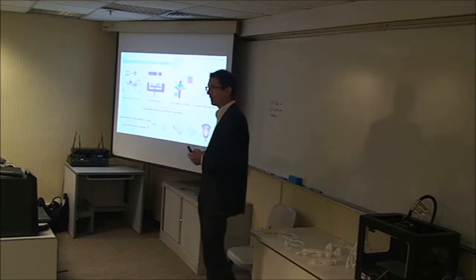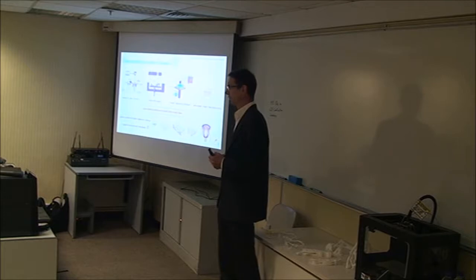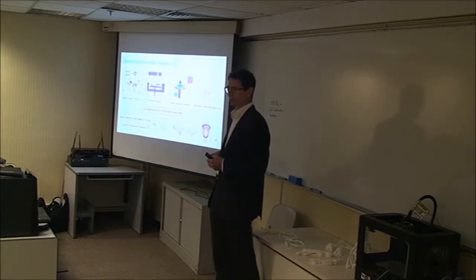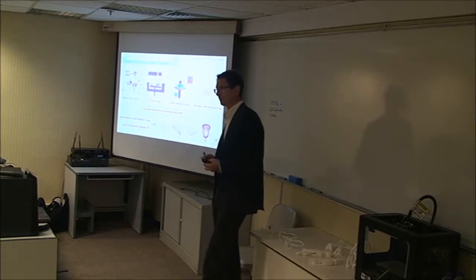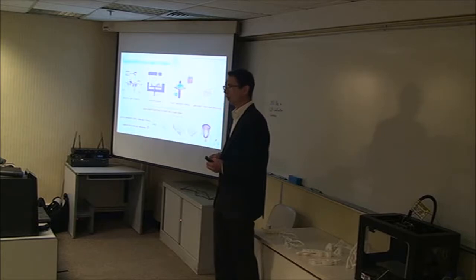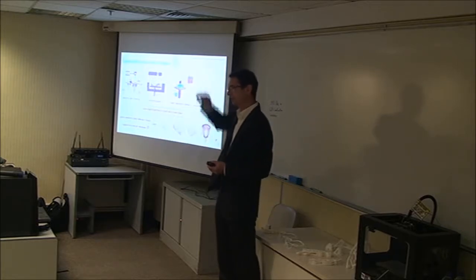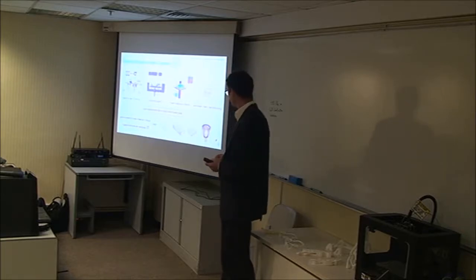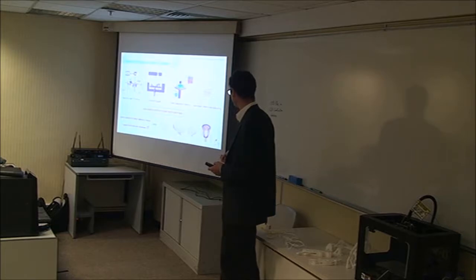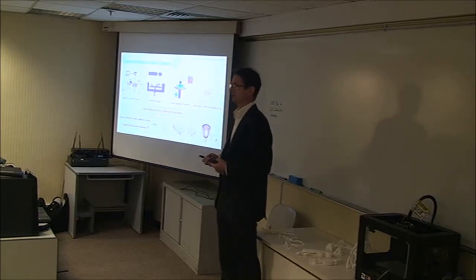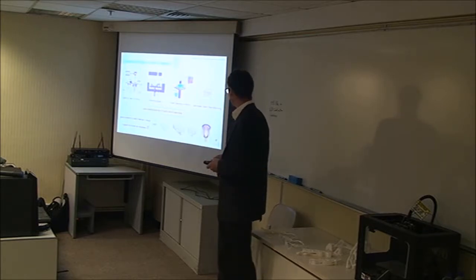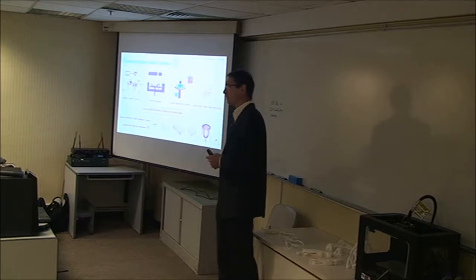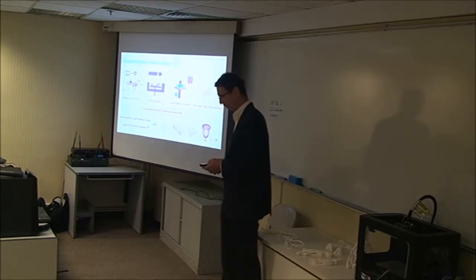But there's one drawback. You have gravity, unfortunately. So when you have a shape without a support underneath, you have to add some support structure. That is necessary maybe later on when you bring the design into the printing process. Most printers, as far as I know, print in just one direction, mainly in Z direction, so against the gravity vector. Therefore you need the support structure that you have to consider, and you have to consider as well to take that out later on. Maybe you can place the part in a different way in your printer, so you print it in different directions, which can save material or can add more material for support structure. That depends.